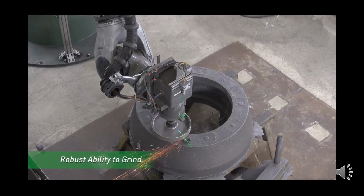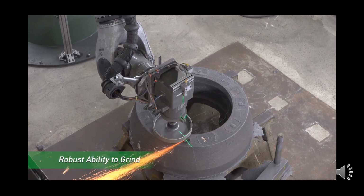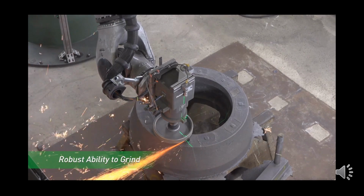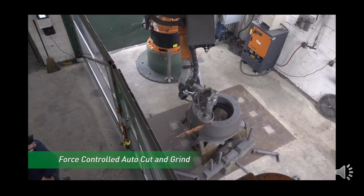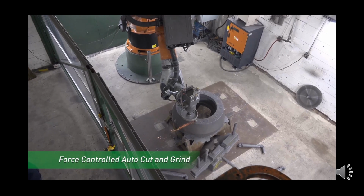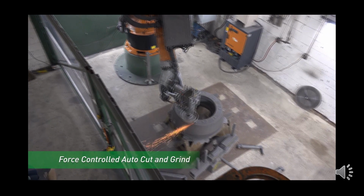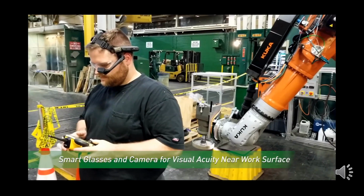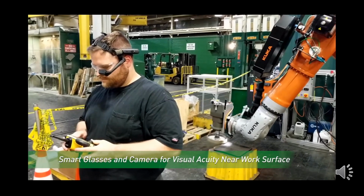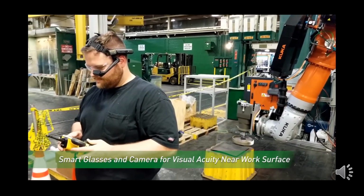It utilized the standard force torque feature to manage cutting feed speed to stay within process limits. It also enables the operator to control feed speed with haptic feedback to warn when he is exceeding proper limits. The system can be set up to follow a surface to ensure quality. It even gives the capability to do remote teleoperation with a camera.